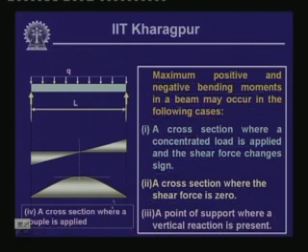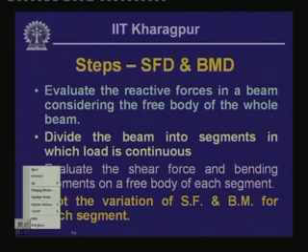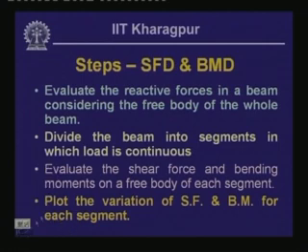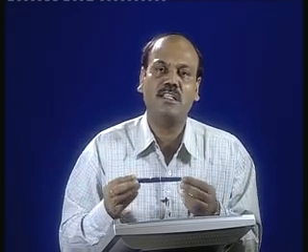Okay. Now, having known these aspects of the bending moment and shear force diagram, we are now in a position to summarize the steps necessary for drawing the shear force and the bending moment diagram. Now, given a beam with certain kinds of loading and with certain kinds of support conditions, and of course, the reactive values of the support should be such that they can be evaluated using the equations of statics. That means, they are statically determinate systems.